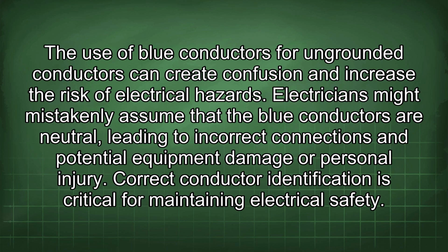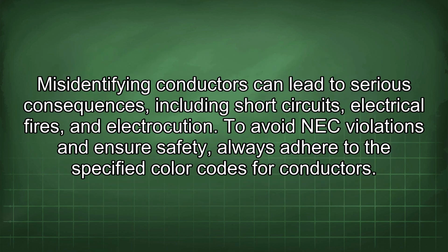The use of blue conductors for ungrounded conductors can create confusion and increase the risk of electrical hazards. Electricians might mistakenly assume that the blue conductors are neutral, leading to incorrect connections and potential equipment damage or personal injury. Correct conductor identification is critical for maintaining electrical safety. Misidentifying conductors can lead to serious consequences, including short circuits, electrical fires, and electrocution.